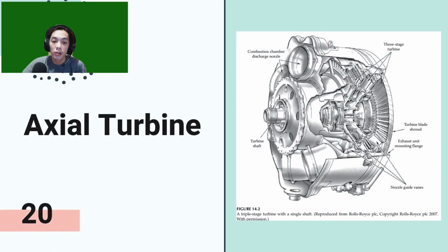The turbine is composed of a few stages. Each has a stator, called nozzle guide vanes, and a rotor blade row of small airfoil-shaped blades. The stators keep the flow from spiraling around the axis by bringing the flow back parallel to the axis. Depending on the engine type, there may be multiple turbine stages present in the engine.